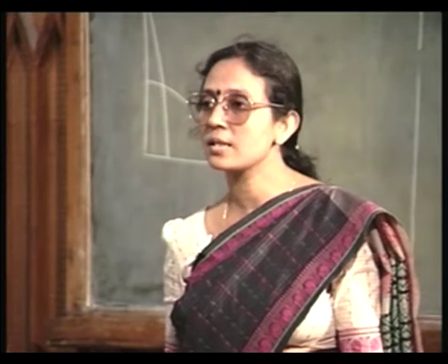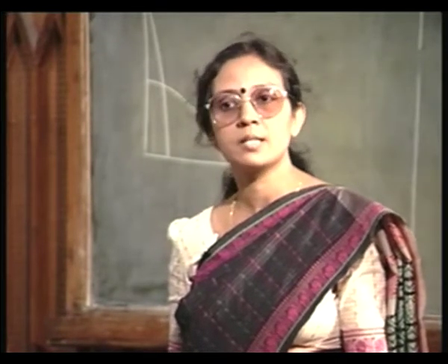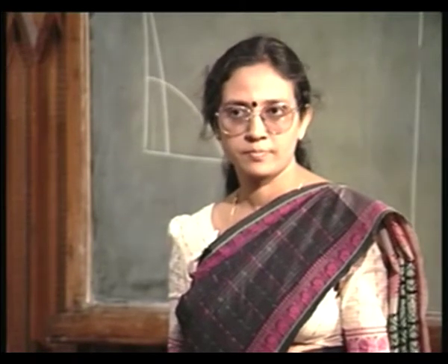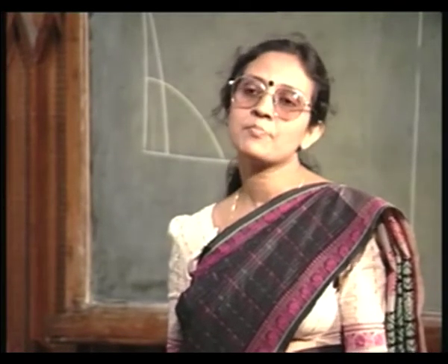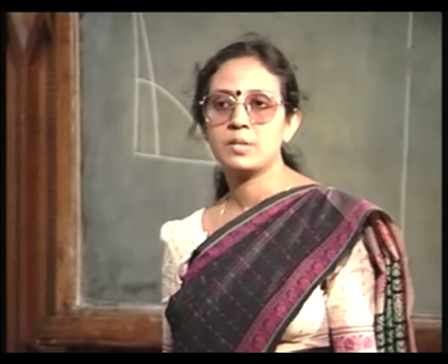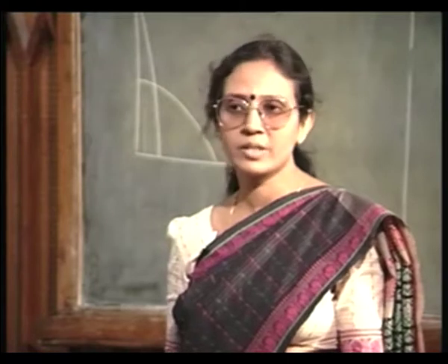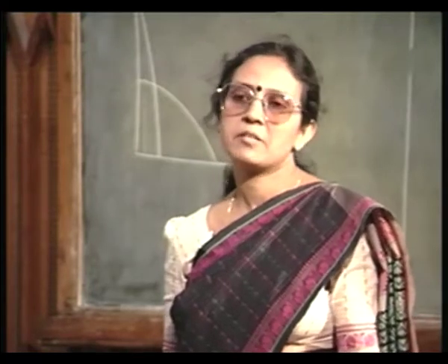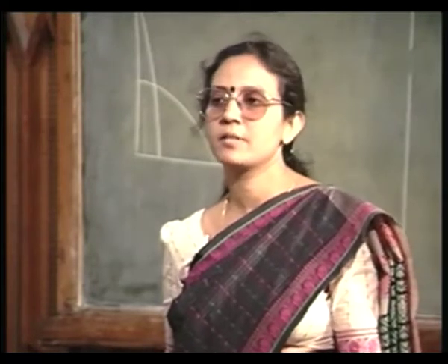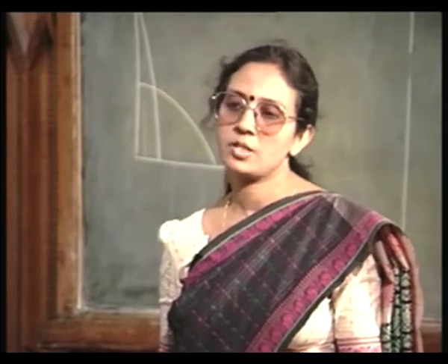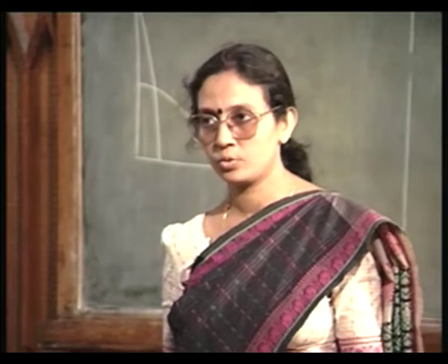You are heating the silicon surface with this high energy beam. Fortunately, these damages can be thermally annealed, not at very high temperature. By 800, 850, maximum 900, 950 degrees centigrade, most of the ion implantation damages can be annealed out.